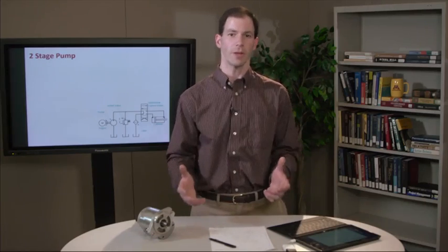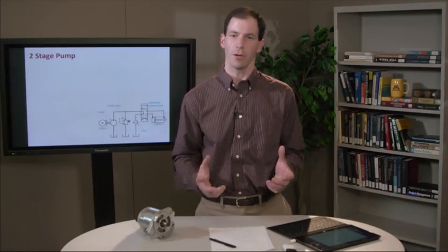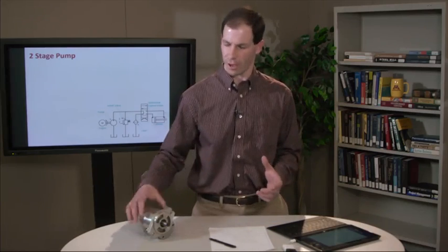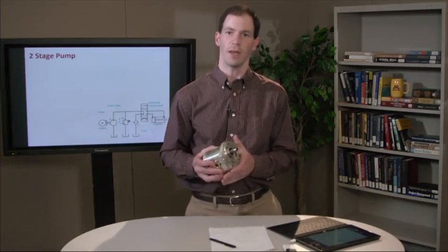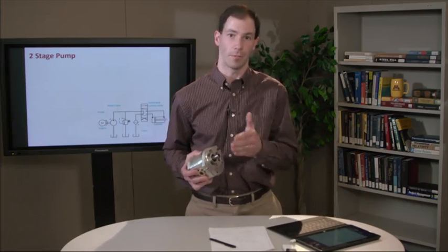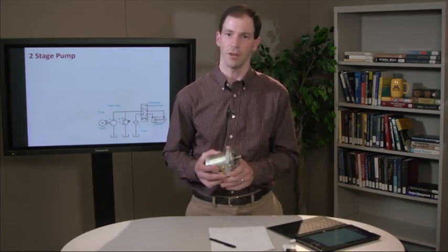All right, so welcome back to the studio. Now that you saw that log splitter, you might have noticed some things that didn't quite jive with what we were originally talking about with a positive displacement pump. So first of all, what did jive is that as we increased the engine speed, the velocity of our hydraulic cylinder increased, both in extension and in retraction. But we noticed that as the force increased, when our hydraulic cylinder started encountering the log, the velocity drastically changed. What was going on there? Remember I was saying the velocity should not change.